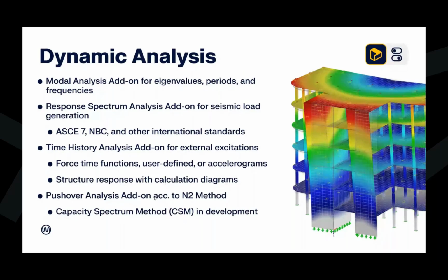Now, with that said, we certainly have had a high request for more simplified building structures and the equivalent lateral force procedure. This is something that we will also implement in the future, and development with that has already begun. We have our third dynamic add-on, the time history analysis, and this is for external excitation. So we have the ability here to define this force time function, or it can be user defined, or we can choose from an accelerogram library if we would like to replicate this seismic load on our structure.